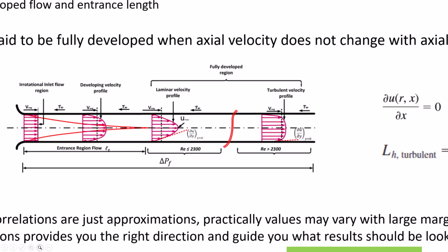In turbulent flow, where the Reynolds number is greater than about 4000, the flow is surely turbulent. But at 2300, the flow starts to change, transitioning from laminar to turbulent. In this case, the velocity profile is highly different. It has sharp gradients at the wall, very sharp compared to the laminar flow. But in the middle region there is a maximum velocity, which is flatter than in the laminar flow. The ratio of maximum to average velocity varies between values like 1.2 and 1.1 depending on the Reynolds number.